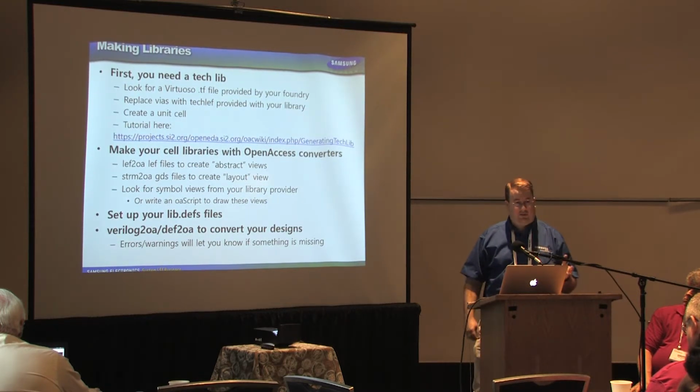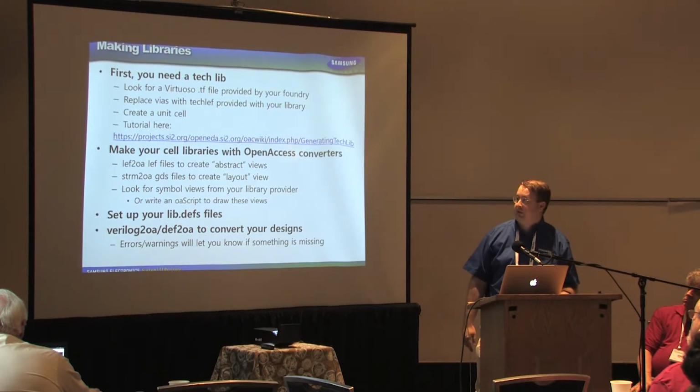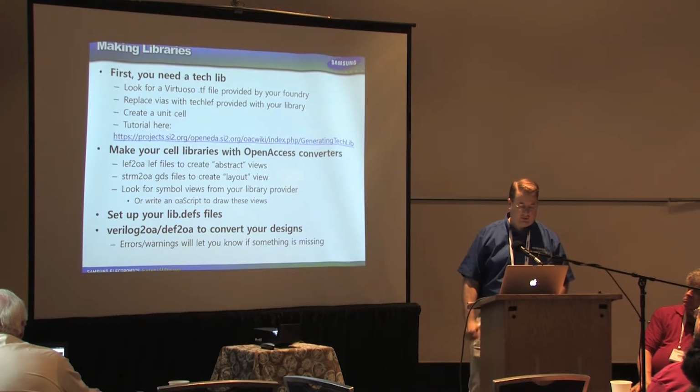After that, you have libdef files, which just specify a list of all the libraries involved. And then the key test is once you start doing Verilog to OA or DEF to OA of current designs, errors or warnings will let you know if you're missing vias, if you're missing cells, if you're missing any components. So just watch errors and warnings on that, and if you can get through clean, then you're usually pretty good on that, and you can just start using it for scripting purposes.